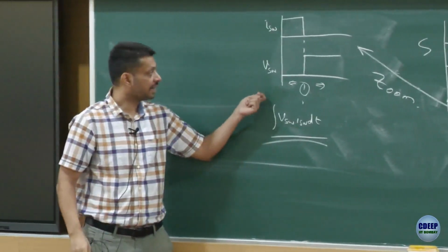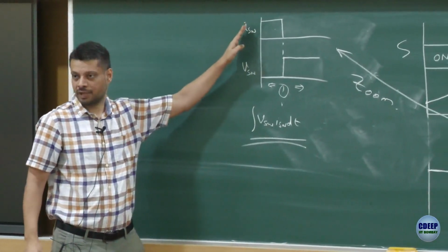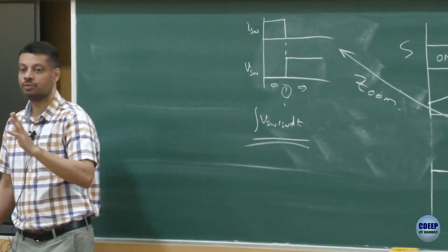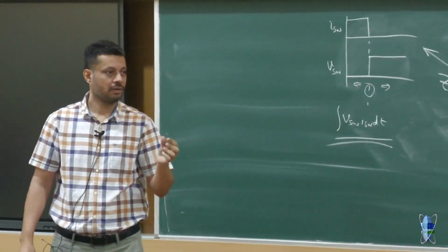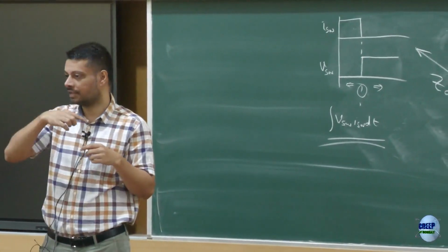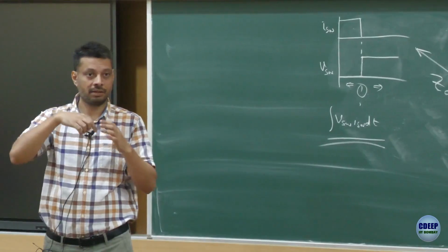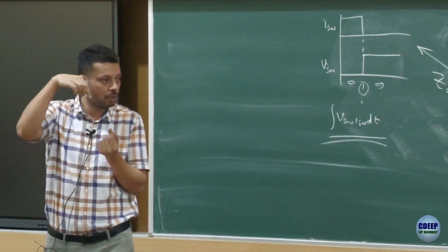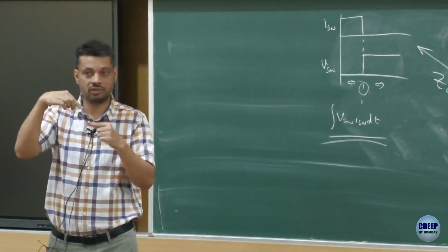If you see the left side, there is a current which is flowing, and voltage is 0, but it is not exactly 0 because the switch will have some resistive drop, because the current will flow through its channel, it will flow through the depletion region and the substrate and so on, and it will flow through the small wires which are connecting the switch chip inside.